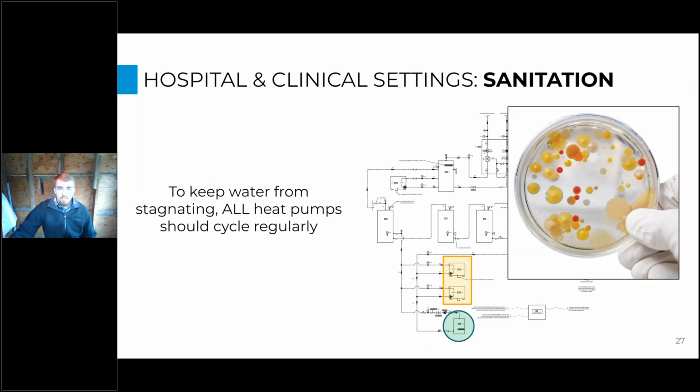When talking about this redundancy, though, we need to keep sanitation in mind, especially in hospitals where we have more delicate occupants. So if we do have redundant heat pump water heaters or a redundant electric heater, we want to make sure that that's not just sitting there turned off with stagnant water sitting in it, right? A lot of controls are capable of implementing these in duty cycles. So it will actually switch off which heat pump turns on first. So it'll cycle through all the heat pumps in that configuration on a daily basis, because each time there's a demand for heat, it'll turn on a new heat pump. That makes sure that there's not stagnant water sitting in these units for a long period of time.